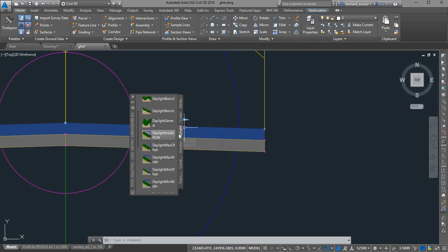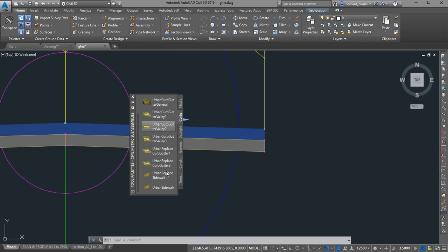Now you have, on top of daylight, you see curbs. So let's select curbs. Now there are different types of curbs. Which of these curbs do you want to use? Do you want to use urban curb with gutter? There are so many of them. So you have to decide on the one you want. But I want us to use a very simple curb, the non-mountable, the normal rectangle, the very simple one. That one you find under basic.